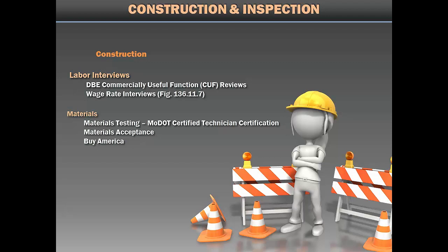Here's what may happen if you allow them to be unloaded and you even pay for the items. The supplier has everything they need from you. It's going to be an absolute pain to get them to get you the mill certification. After confirmation that you will be getting the mill cert, you allow the girders to be installed, then the bridge crew gets the deck poured. Weeks go by and still you don't have the mill certs for the steel.